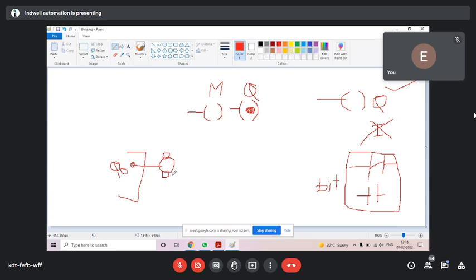In your program, if output coil is on, something will get on outside of PLC. But in your program, if any flag gets on, there will be nothing on outside of PLC called flag. So it is internal bit memory. I hope you understand. So similarity you understood, and difference also you understood.